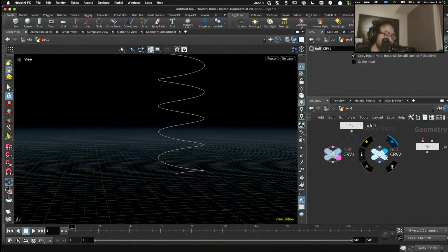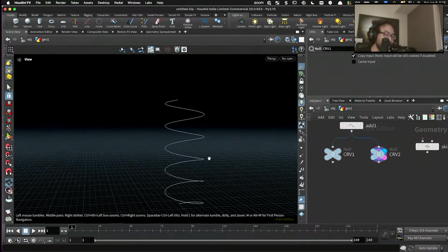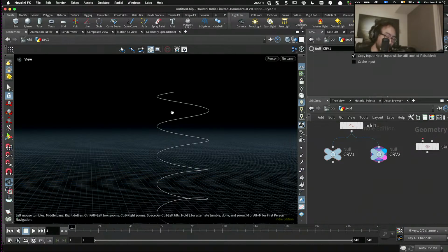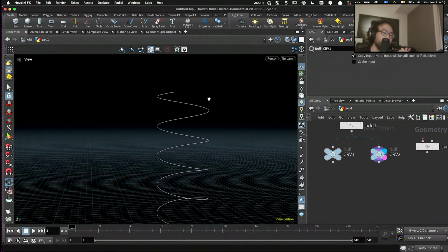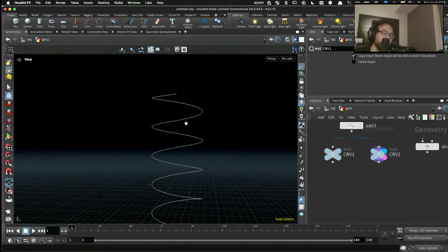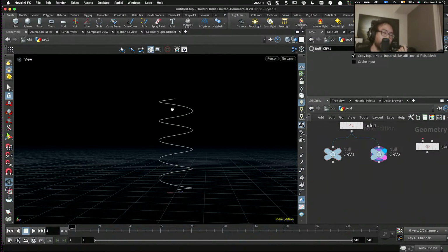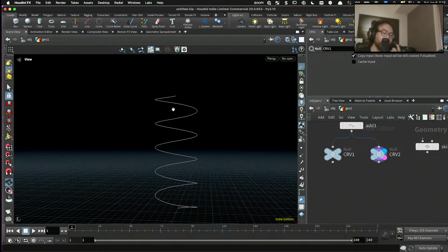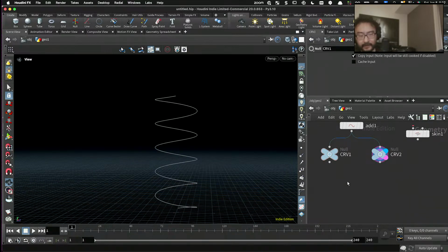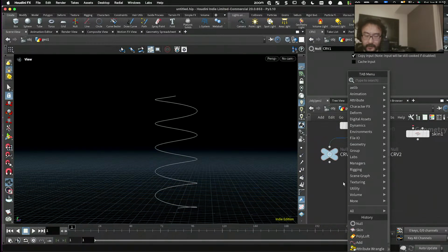And on the right-hand side, for curve 2, I'm going to trim out the top part, the same one-turn region, which is around 360 degrees. By doing that, you keep the total number of points the same for curve 1 and curve 2, which enables you to use skin in some way to connect these curves together. Okay, that's my plan.